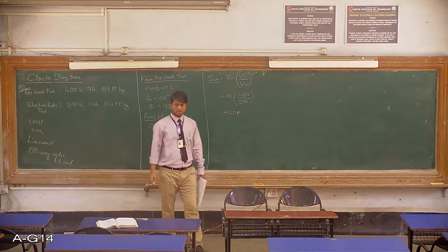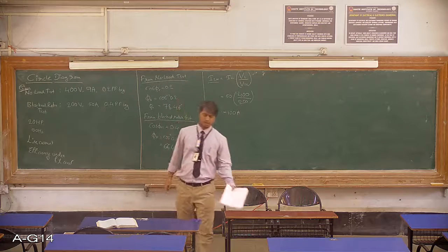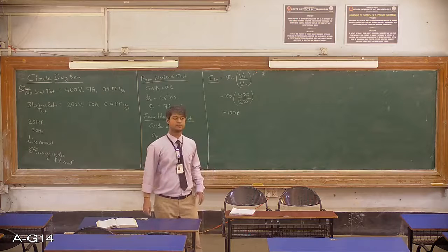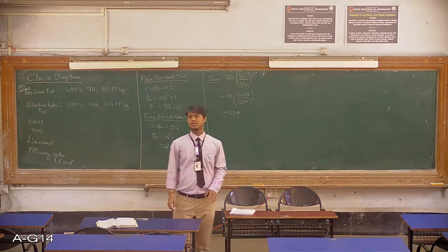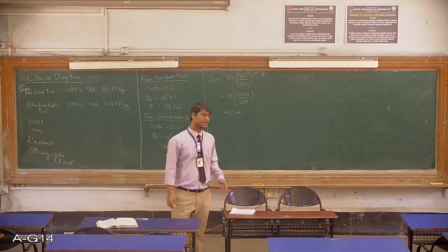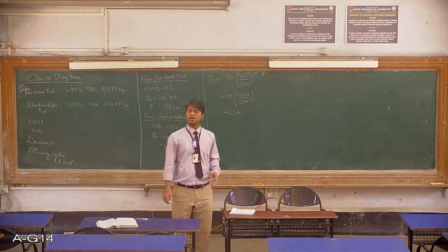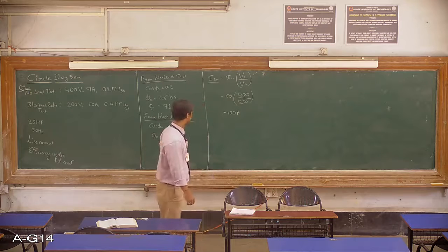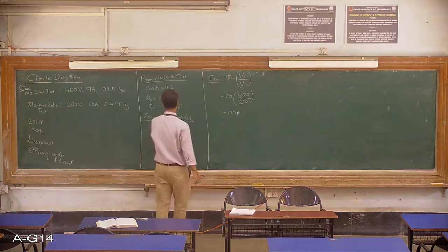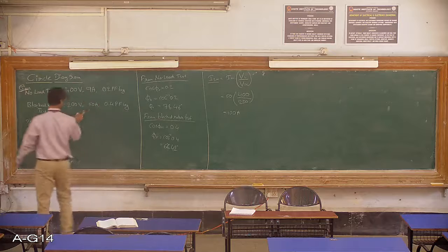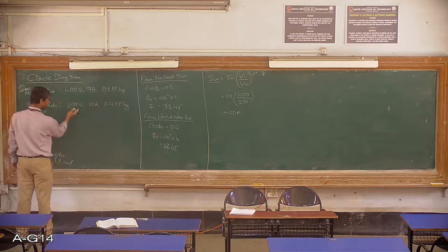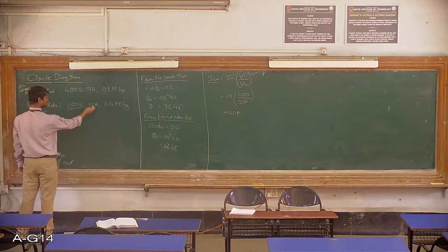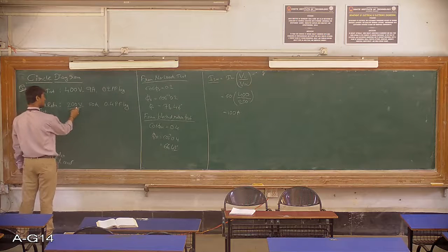Here we cannot conduct the experiment to get to know what will be the short circuit current under normal voltage, because under blocked rotor test the rotor is blocked, it is as good as a short circuit. Under short circuit condition we cannot apply the rated voltage to the machine. So we only had the short circuit current under reduced voltage. This is not the full voltage of the machine.